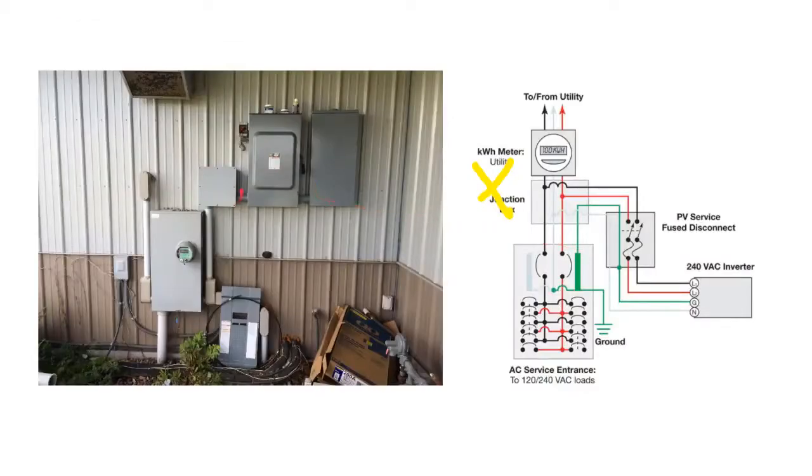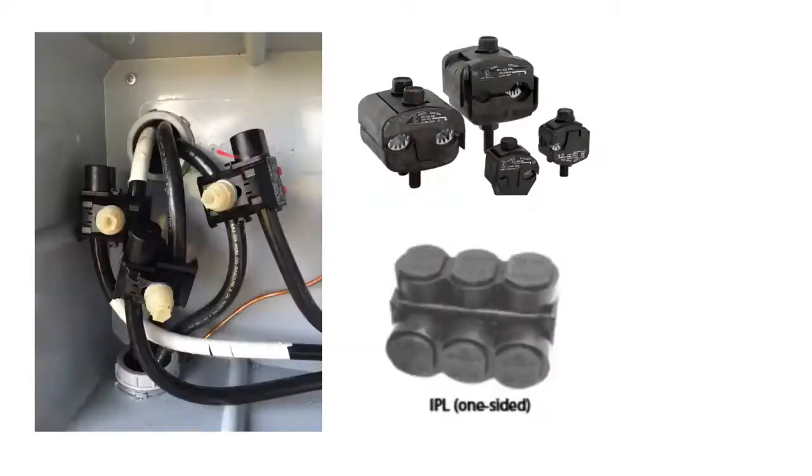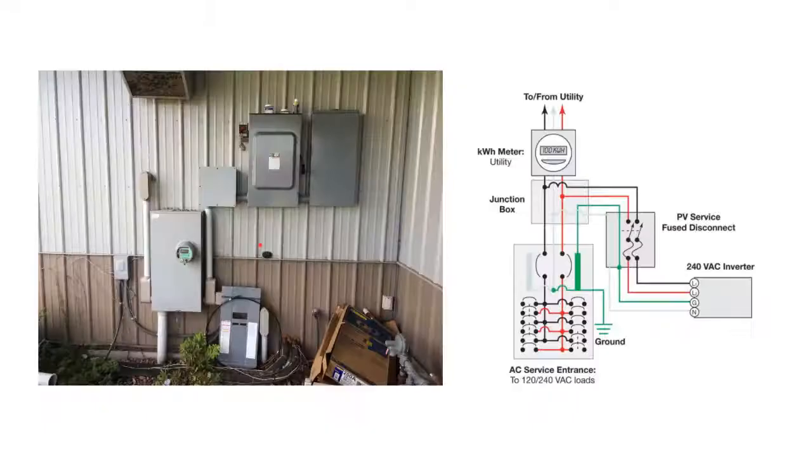This process was scheduled when the building was not in use, and it took less than an hour. So when the solar array was ready to install, all that was needed was to open up the junction box and tap onto the conductors, a process that took only a few minutes. Minimal business activity was interrupted as a result of the supply side connection.